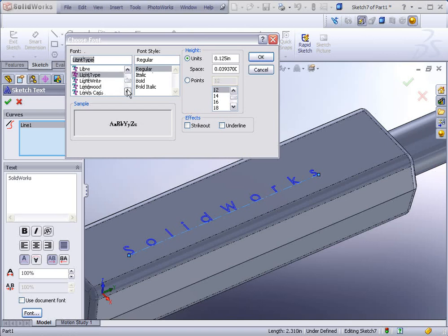And let me see, generally if you just want to make sure it works quickly, Impact or Haettenschweiler work very well, or Arial. I'm going to use something called Arrow. Okay, do not use the bold or bold italicized in this option. Generally it will cause a failure of the geometry simply because it starts to intersect each other. So stay away from that. But you can use the regular italic. I'm just going to keep it, I will use italicized.